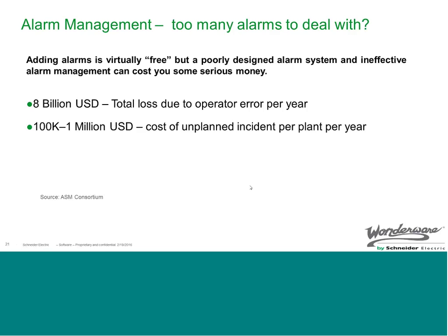So what Wonderware has is called Alarm Advisor. And it allows you to get rid of your nuisance alarms. It allows you to clean up your alarming system. It's too easy to create too many alarms that don't require operator action. And so the problem when you have alarms that don't require operator action is the important ones get missed. And when important alarms get missed, it costs us money. It costs us downtime. There's incidents, and that's what we really want to avoid.